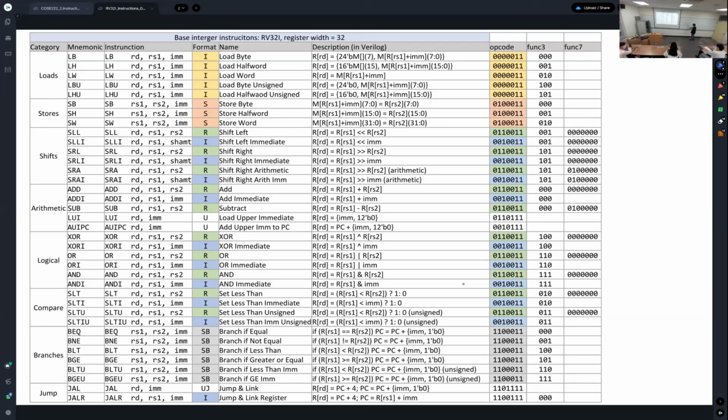But as I mentioned, we can use a negative integer like -4. So it's easy. We can just use -4 as the offset of this store or load instruction, and we can perform 1000 minus 4. This is 996. Okay, you understand? So a signed number means that we can use a signed integer as the offset, and then we can just perform the add operation for calculating the address of a load or store instruction.